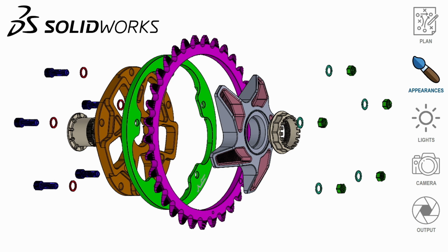So knowing that I was going to do that while I was in SolidWorks, I just took those faces or features and applied those appearances in there so that I have quick access to that. And then I can just switch that appearance right out and visualize and not have to worry about trying to split off faces and visualize or anything like that. All right, so again, probably a semi-unorthodox way to do things, but I find that it helps quite a bit.